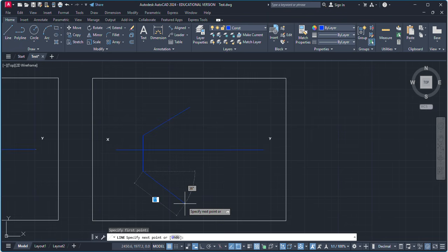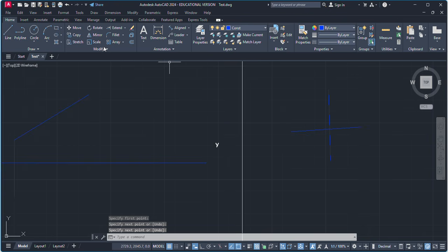So in the downward direction from C, these are 4 quadrants, and from this right side, if you move upside from here to here, it is 90 degrees, 180, 270. So in this direction, the anti-clockwise direction, the angle is positive. If you want to create a line here, suppose this is at 45 degrees, you just need to enter the angle 45 degrees.